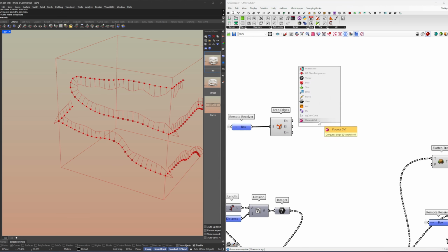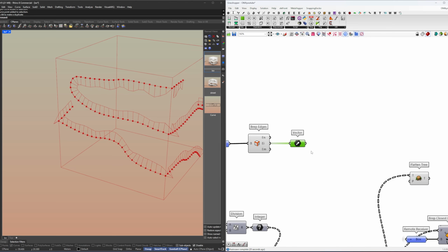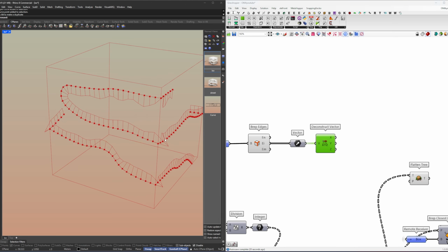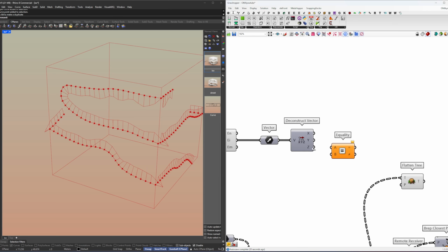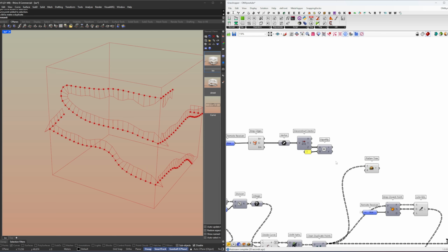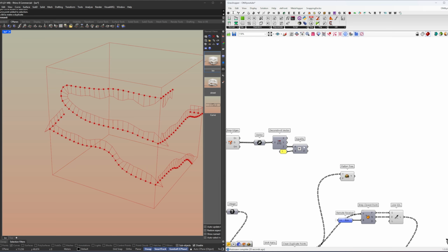And if I check the vector of these curves, because it automatically creates a vector in the direction of the curve, we want this vector to be either 1 or -1, meaning it either faces up or faces down. I'm talking here about the Z, by the way. So we're going to say this one equals 1. I see 1 is the way to go actually. We can also say or equals -1, but in this case it's not going to matter anymore.